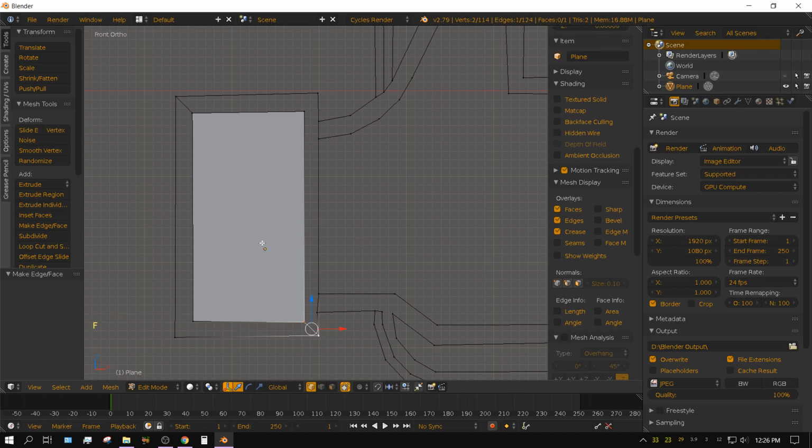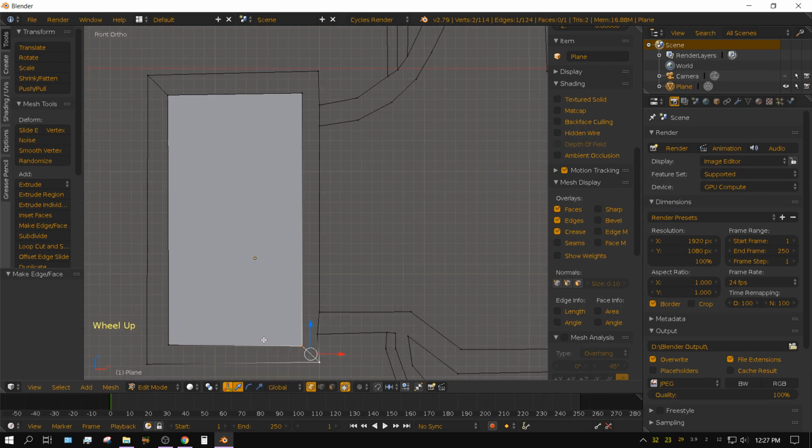And the reason why we're doing that, we have to break this up in two different pieces. That way this is a separate face and this over here is a separate face. Otherwise, when we go to fill it, it will fill all the way across, and we don't want to do that. So now that we got that sorted out, and I hope I didn't confuse you too much,